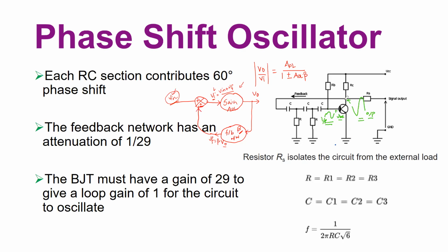The idea is you can have one more amplifier stage right here, but there is no feedback. You can add one more common emitter stage here and again invert this output to get a 360-degree phase shift, so your output will be in phase with this one. But where is the feedback? Without a feedback, you don't really have any oscillation criteria, because there is no loop. It is still an open loop circuit. For an oscillator, you need a closed loop circuit.